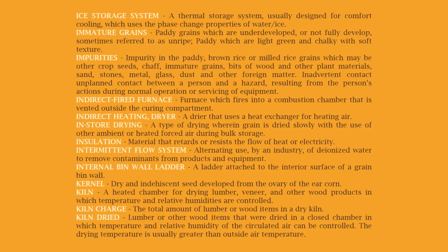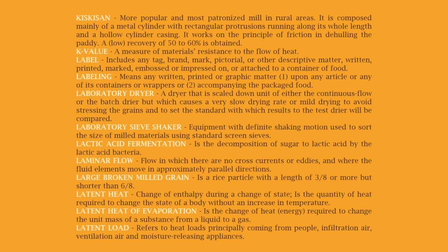The drying temperature is usually greater than outside air temperature. Kiskisen. More popular and most patronized mill in rural areas. It is composed mainly of a metal cylinder with rectangular protrusions running along its whole length and a hollow cylinder casing. It works on the principle of friction in dehulling the paddy. A low recovery of 50 to 60% is obtained. K value. A measure of material's resistance to the flow of heat.